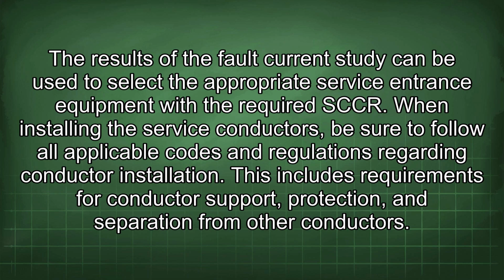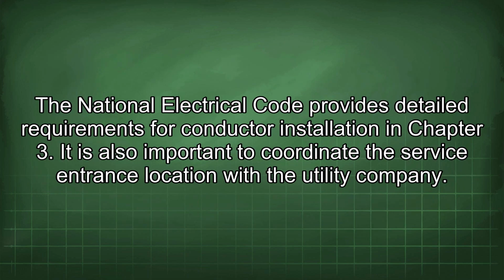When installing the service conductors, be sure to follow all applicable codes and regulations regarding conductor installation. This includes requirements for conductor support, protection, and separation from other conductors. The National Electrical Code provides detailed requirements for conductor installation in Chapter 3.